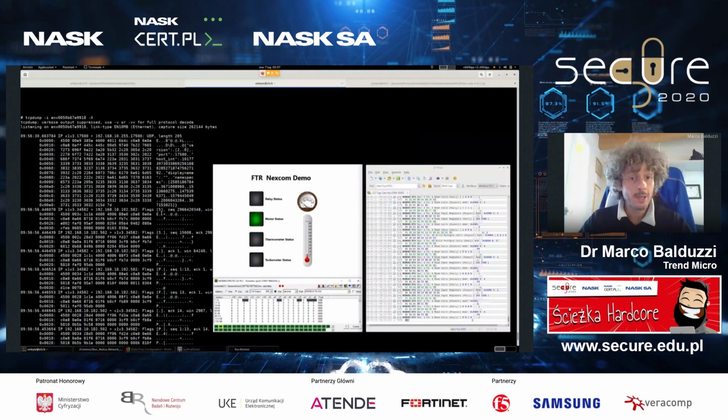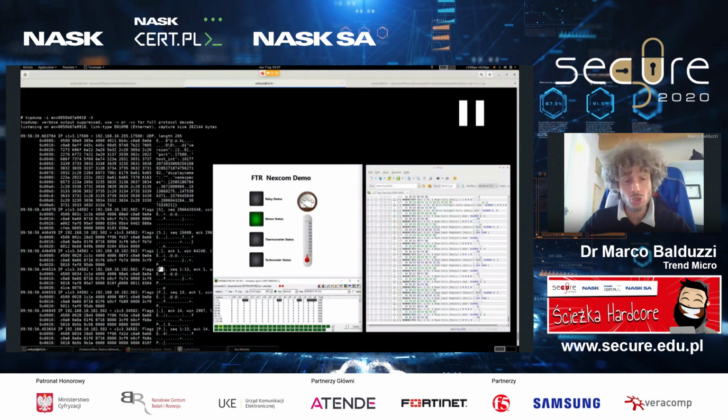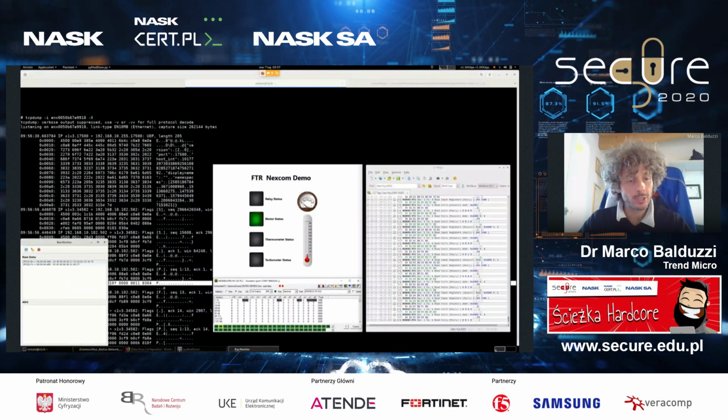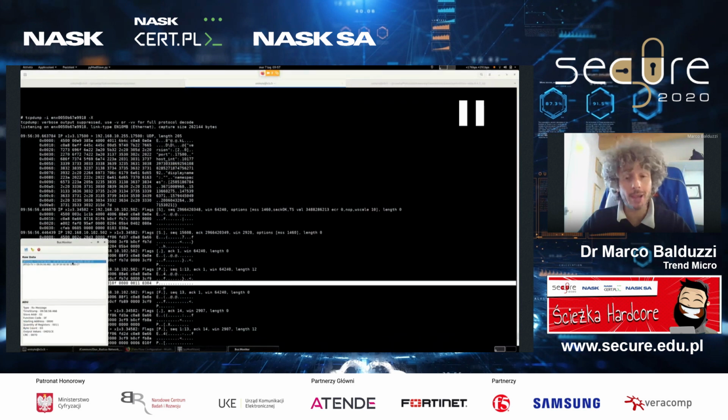So that's super severe. And I'm going to show you here in the push request of the Modbus TCP, the packet generated by the attacker. And on the serial, you can see that the packet received by the PLC is the same as the attacker's. So the problem here, again, is that the gateway, instead of removing the Modbus TCP header, taking the payload, computing the Modbus RTU checksum, and doing an actual translation, takes the original packet as it is and converts it down to the slave.